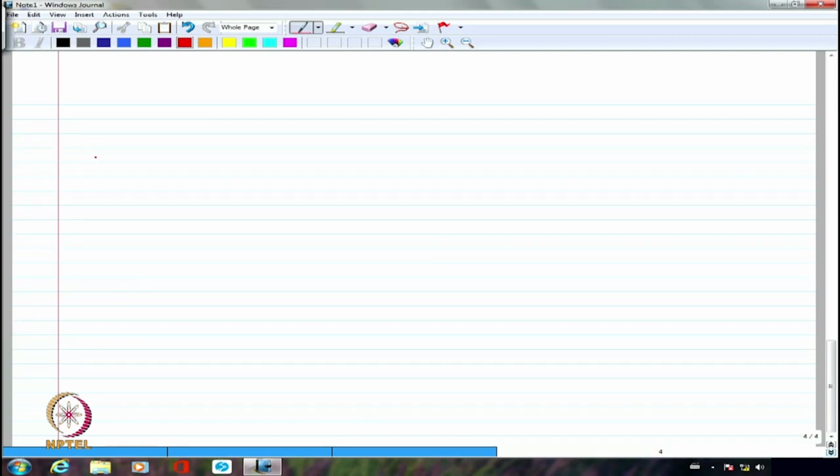So, let us say this is my Ef for a generator. Maybe my current is somewhere here. So, what I need to do is to first of all construct the triangle corresponding to Ia Ra, if at all I am looking at resistance also.